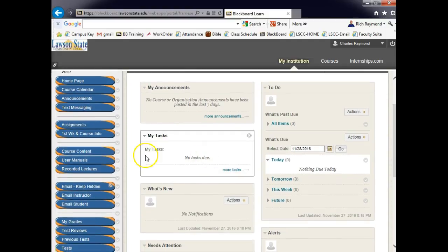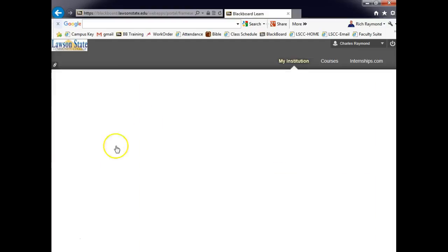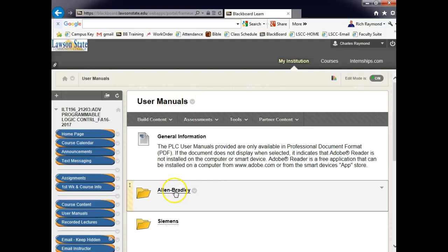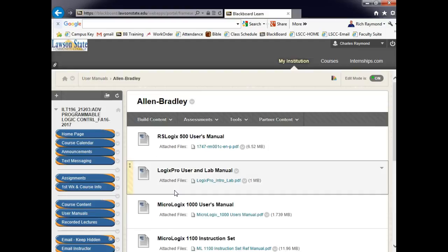Okay. So user manuals. Is that some things in the PLC, I can make changes without downloading? Like if I change the number on the operand, I don't have to download it. But on some of them, I have to go offline to make that change and then download it.